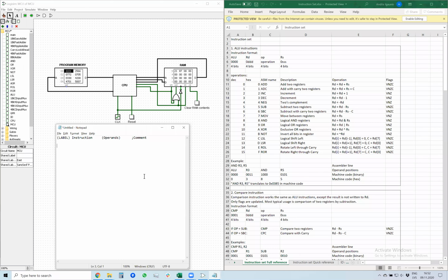Okay, so let's just write a simple assembly code and check out how it's being constructed and how it's being executed in the CPU. You will also have to do this, so I'll do something and then I'll ask you to also do something. So the first thing that we want to do: to do anything with some numbers in the processor, we need to get those numbers inside the CPU. Okay. So how to get numbers inside the CPU?